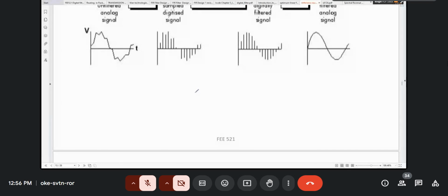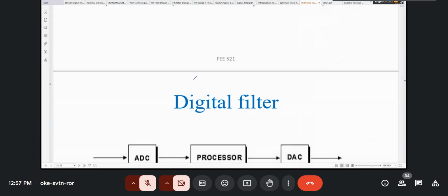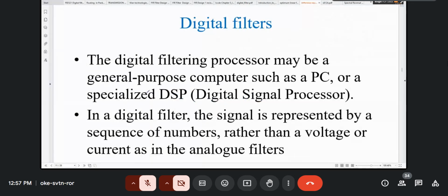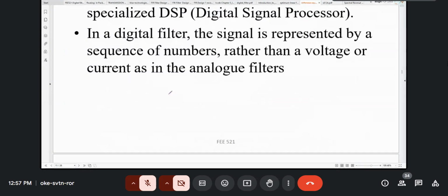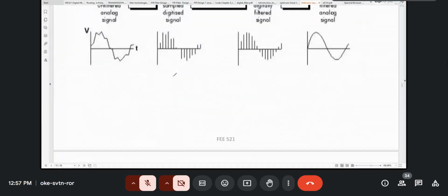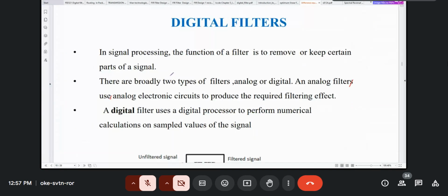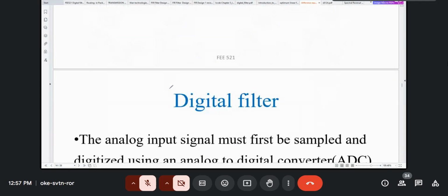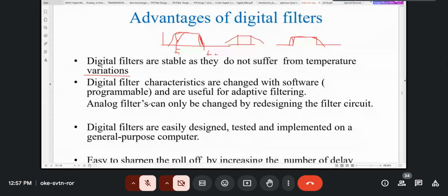You're going to see in some cases you're going to have certain coefficients as 0, some certain coefficients as 1. And of course, when we put it in the form of a difference equation, we only put the coefficients which are either positive or negative. We don't include the ones which are 0. But remember, when you come up with the coefficients, you'll have a number of coefficients. Some of them will be 0, so they will not appear in the difference equation. It simply means the ones which are not mentioned are 0. I think that will become clear when we come to actually designing a filter.